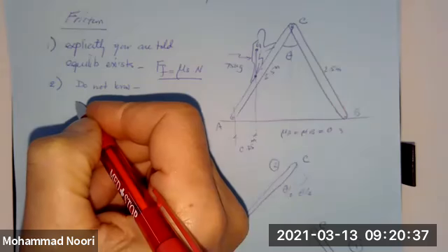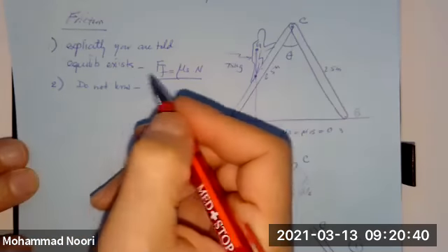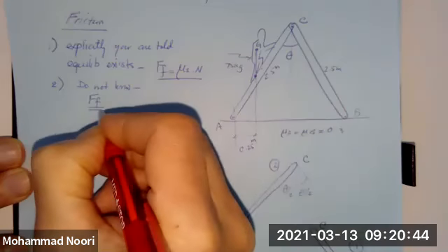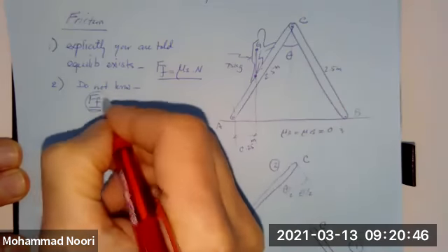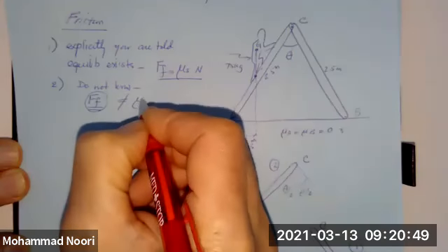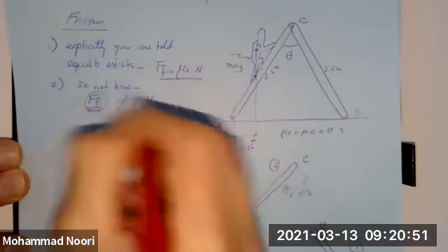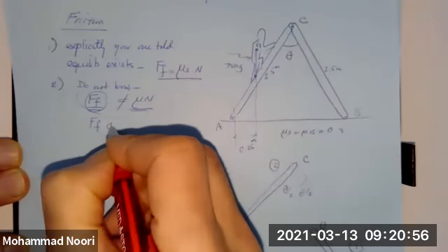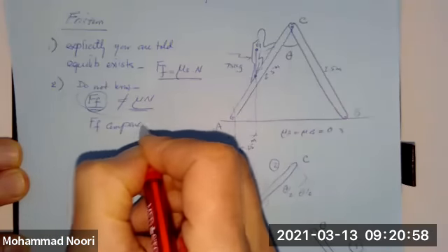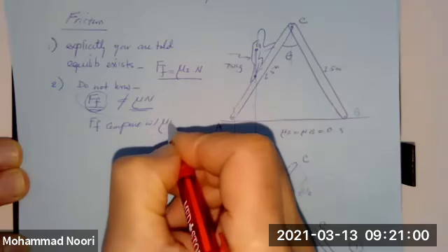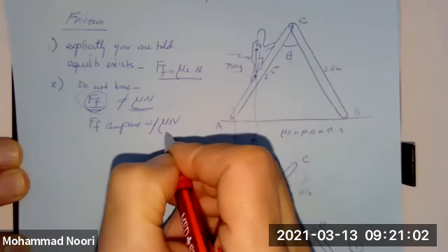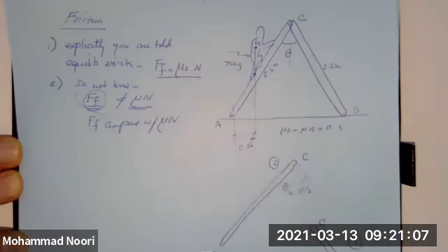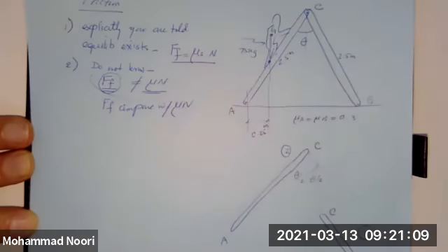So you solve the problem based on the assumption of equilibrium. However, the friction force, wherever it exists, is an unknown that is not mu s. You need to find that as an independent unknown, and then compare that with mu s N. If it is less than or equal to that, then equilibrium exists. If not, it doesn't.